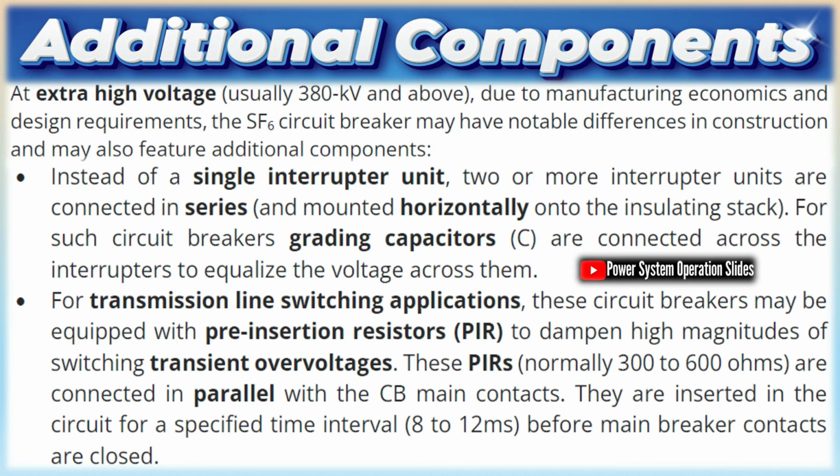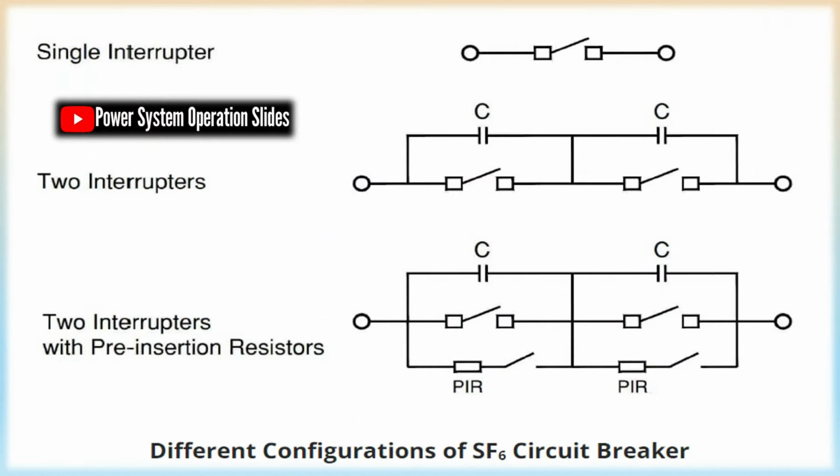When the sinusoidal current waveform approaches zero, the arc becomes relatively weak and the pressurized SF6 gas inside the puffer cylinder flows axially through the nozzle over the arc length. This blast of SF6 gas removes the thermal energy in the contact gap and reduces the degree of ionization and electrical conductivity, such that the arc is extinguished.